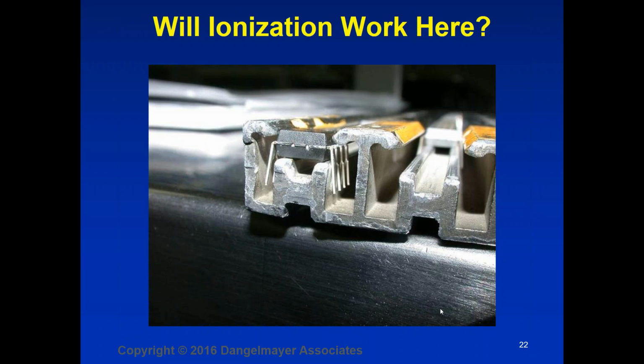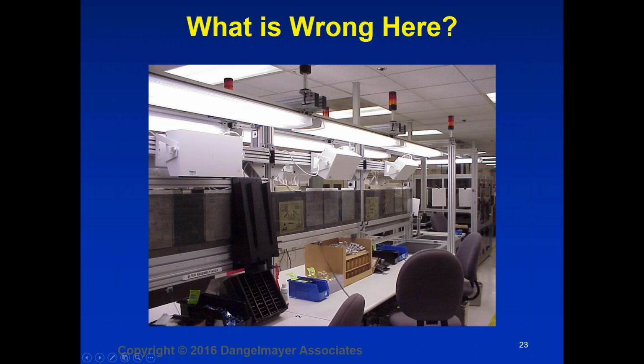Next slide. Here's a question you may have answered already, but just to be sure: how is the best ionizer position determined? Well, first of all, the best ionizer position is the one in which the ionizer is directed at where the work is going on. You want the ionizer to be positioned so that the ionized air reaches your sensitive product. That's the main thing. What you will also be doing in terms of your application of ionizers is making measurements on them. You will be able to measure what the performance would be in the area that you're working on, and you might use that same performance measurement to redirect the ionizer in some way if its position is adjustable. But basically, you want to direct the airflow to where your work is going on and make sure that it hits the sensitive product.